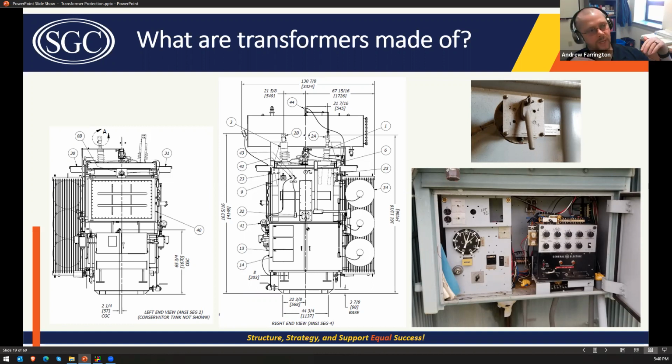Sometimes you'll have a long distribution circuit with customers tapped along the entire length, and you can't regulate the voltage here at the station very well and maintain an appropriate voltage for the customers near the station and the customers a long way away. So periodically they may install more regulators, 5 miles down the distribution circuit, such that the customers beyond that point have an appropriate voltage.